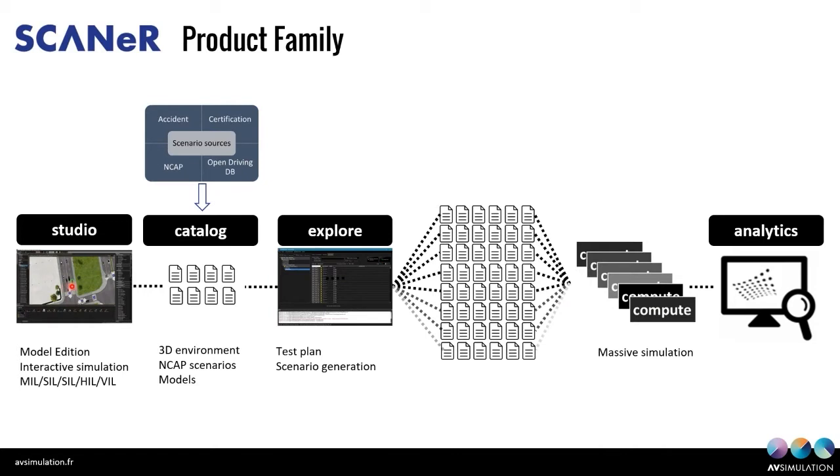In any case, SCANeR Studio is the basic program to begin with SCANeR, because it is from SCANeR Studio that you will be able to build your scenario, define your metrics to record, interface your vehicle dynamics if you have a specific one, build your 3D environment, run your simulation, and define where the simulation will be executed. Is it on a workstation? Is it on a simulator? Etc. So from SCANeR Studio, you will be able to prepare your data, interface your system under test, and then run it.